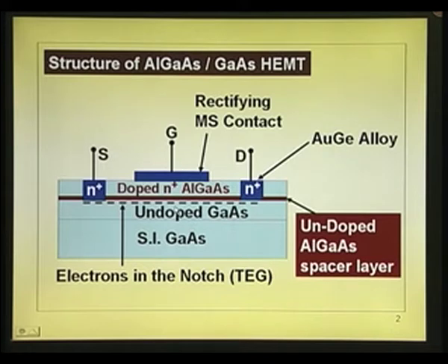And to ensure that this top layer, the heavily doped layer, does not participate in the conduction in any portion of the device operation, you ensure that the entire layer is depleted. Okay. So, what we have computed also is, we have seen that the voltage required to deplete this entire top layer will be VBI minus Vp0, which actually is equivalent of the threshold voltage of this top layer, just when it is depleted.